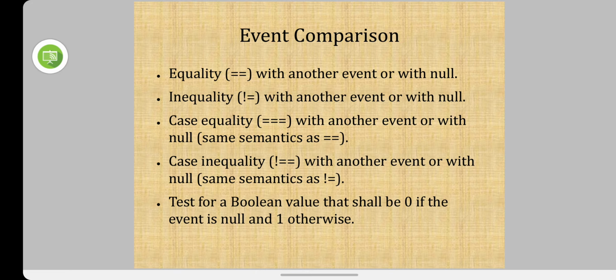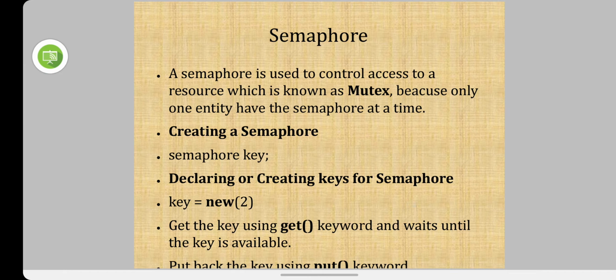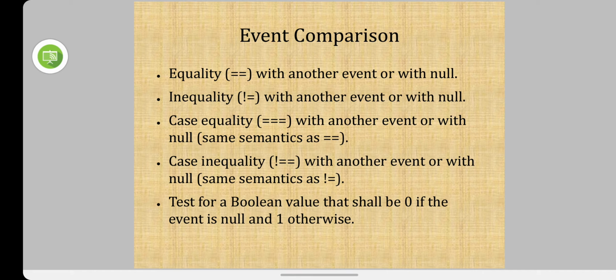Because, as I have already mentioned, there are disadvantages of wait statements and triggering, right? So there could always be a disadvantage of using these events in your SystemVerilog testbenches. So it is best practice to avoid these events, since we have other synchronization methods like semaphores and mailboxes. Okay, so events are completed, and next comes the semaphore. But as I have already told, let's complete the SystemVerilog testbench architecture first, and then we could go to the semaphores and mailboxes later.